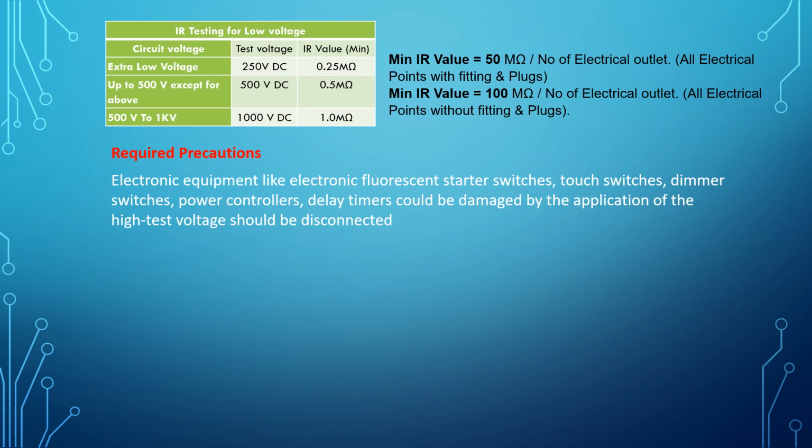That's during our installation testing, our pre-commissioning testing, but during the commissioning, that's the time we need to know whether it's working or not. The only thing that you do during the construction stages is continuity, because of the lower value grade of the cable, that is 0.5. Okay, that's what we need to be very careful about. That is the precaution.